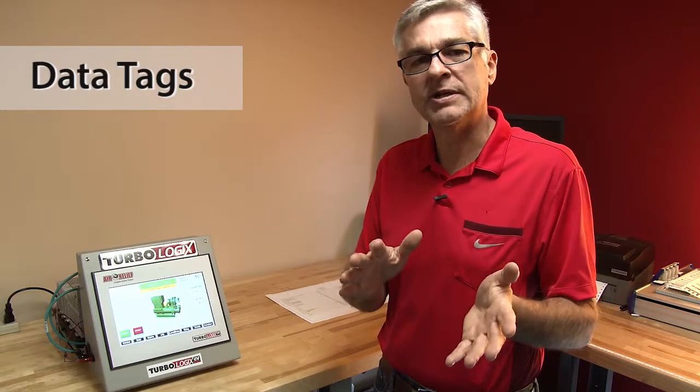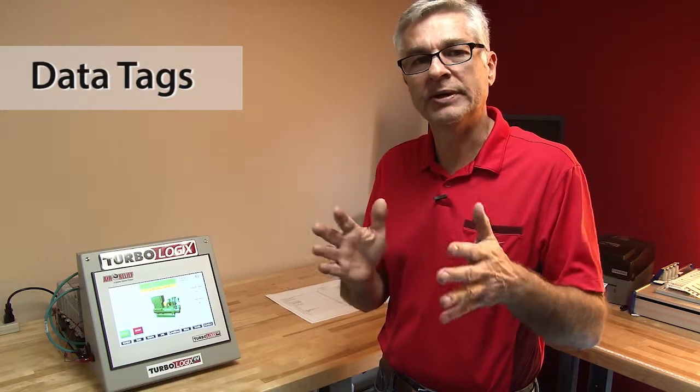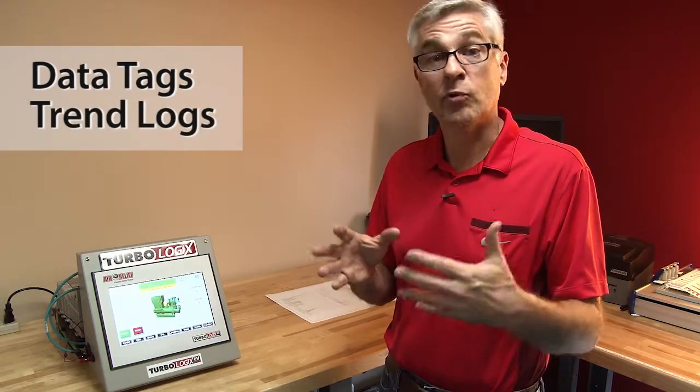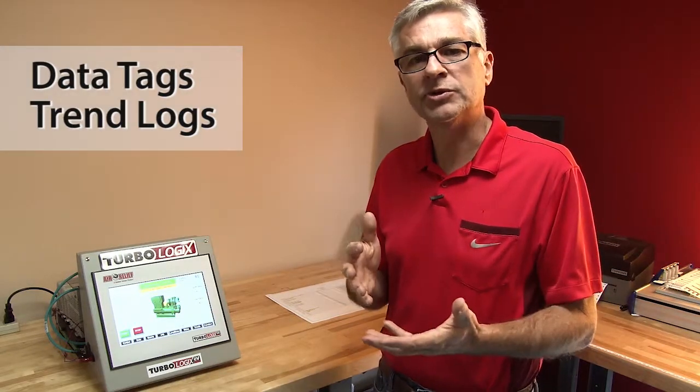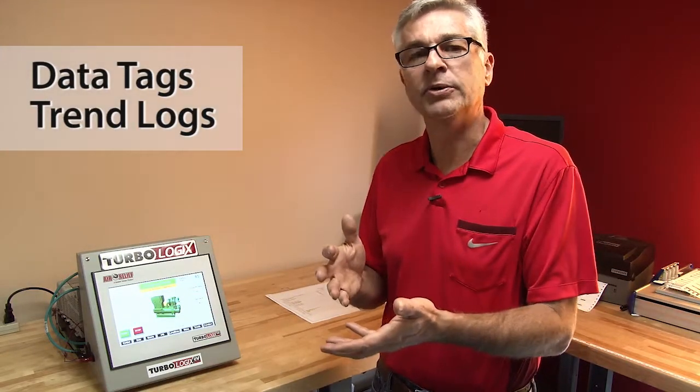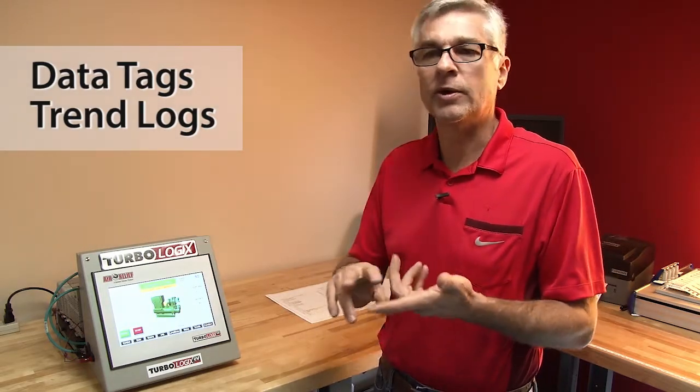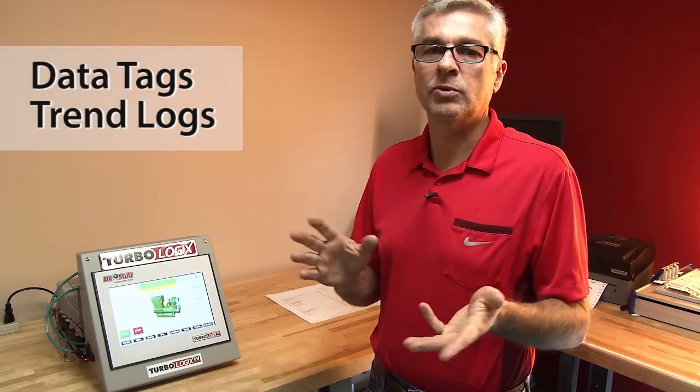And once we set up the programming for that, then whatever unique tag name you've given an input will transfer over into the analog input and digital input data pages. You'll also see on your trend logs, the analog trend logs, any analog input that you've renamed will show up there, and we'll show you some of the areas that are available to add new customized inputs and show them up, for example, on a vibration screen or a temperature screen or a pressure based screen. So we've got inputs there that we can customize and show up.